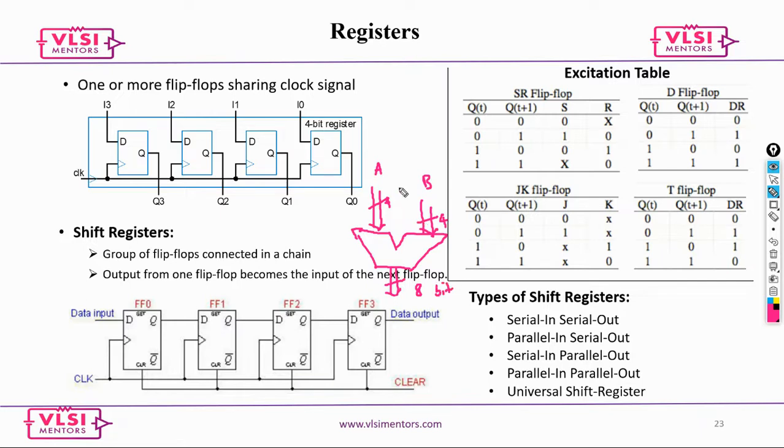Okay, now if the inputs keep on changing, then this ALU will not be able to give you the output. So to avoid that, you clock these values, we call it clocking these signals. If you send them through a register, they are going to be constant till your next clock pulse comes.